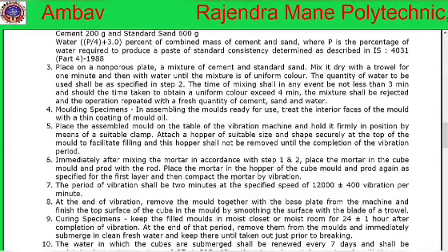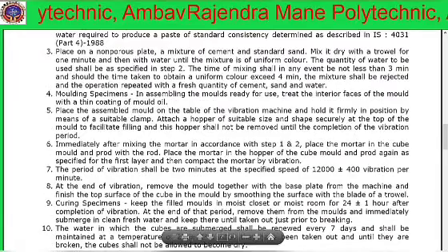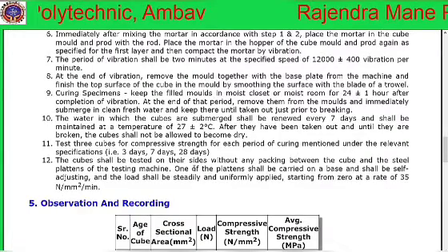Then remove the cubes from the molds after 24 hours and keep them immersed in clean water till the moment of testing. They shall be tested on their sides without any packing between the cube and the steel plates of the testing machine.